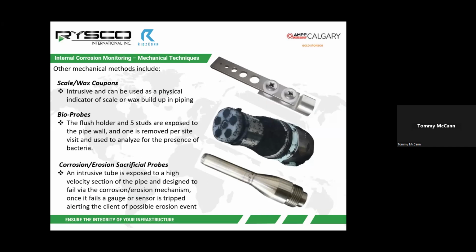A few other ones, less common, but still can provide valuable data. A scale coupon, or in some regions they call it a wax coupon. There's no magic calculation to them. It's a physical indicator if you have scale or wax buildup in piping. Instead of the bladed style intrusive coupon we've seen before on the strip, where you mount two and the blade end faces the flow, the holes in that coupon face the flow, and you're trying to simulate that pressure differential.